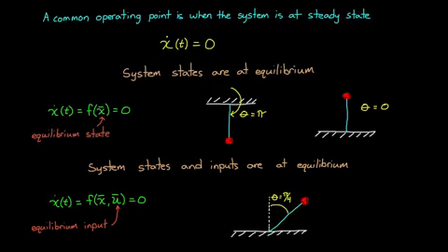If we initialize the pendulum in this condition, it would not move since the torque from gravity and the input torque perfectly balance out, and we can linearize around this condition as well. Now, the act of finding an equilibrium by adjusting the input signals is called trimming. And this is a term that's borrowed from aerospace, like trimming an aircraft to fly straight and level.